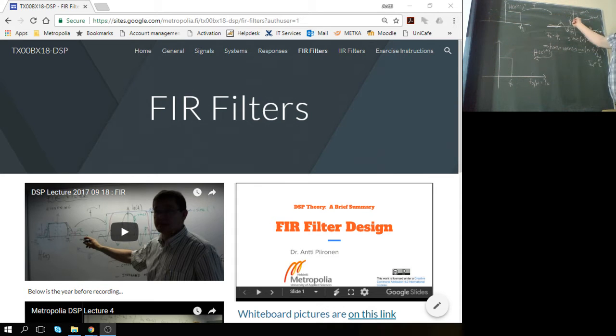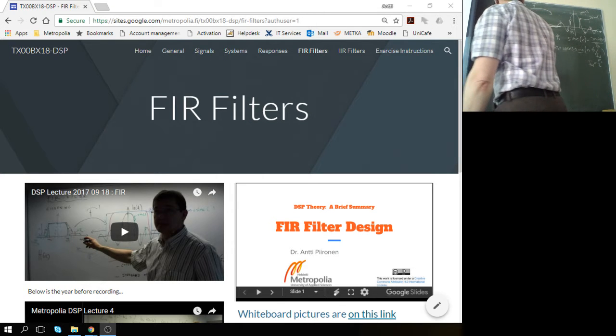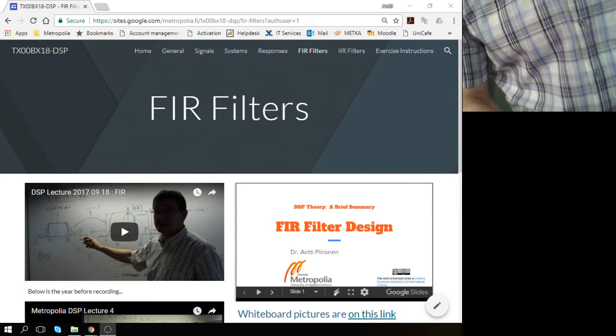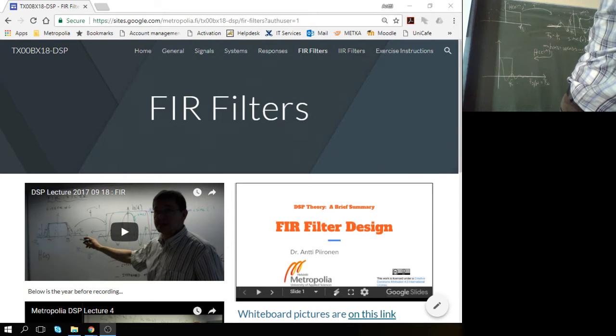The inverse Fourier transform or Fourier transform is the same function. But on the time scale, we multiplied it with a box. The Fourier transform of a box, which is the same as the inverse Fourier transform of the box, is a sinc function, but this time the sinc function is on frequency space. All right, so we have the sinc function here, and the convolution of those practically would give you the final